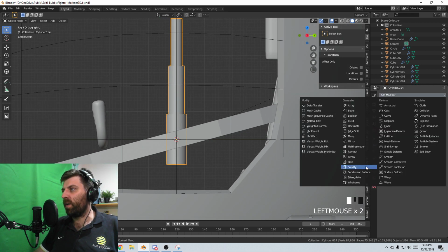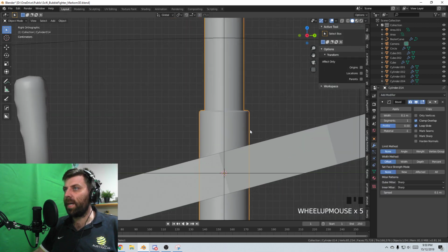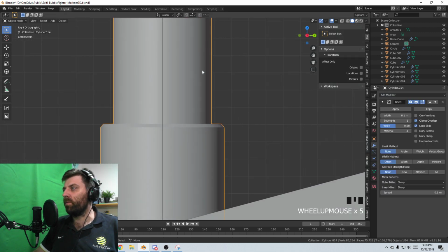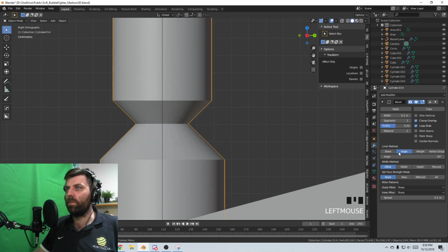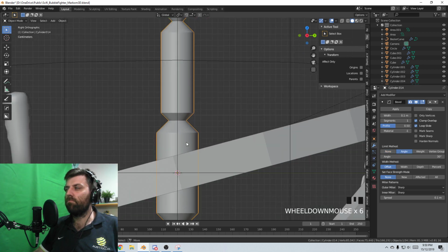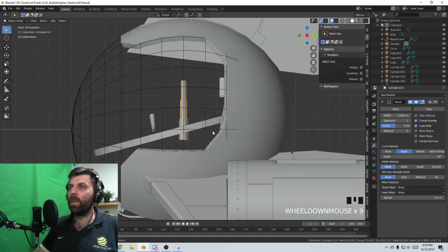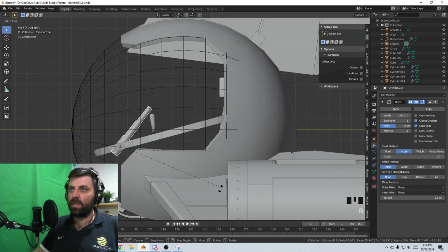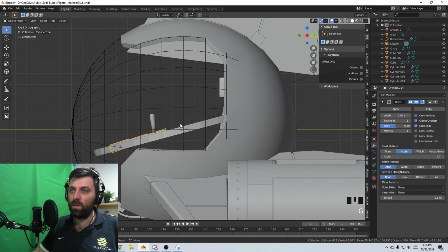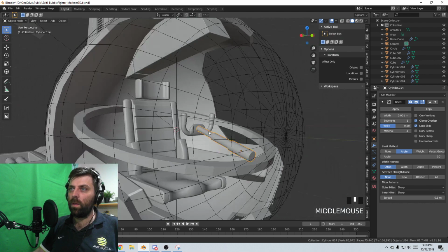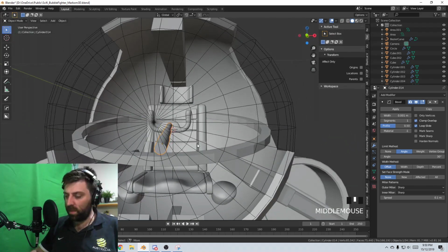Come into the mirror modifier, into the modifiers. Let's put in a bevel modifier. Nice. But you can see we've got all our bevels in there. So we change this to angle. Right. Let's turn that down. 0.01. There we go. And so now technically if we set it up like so, G, it would work like this.